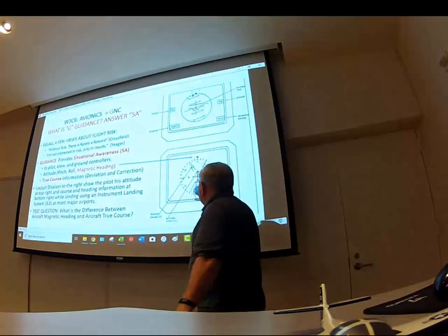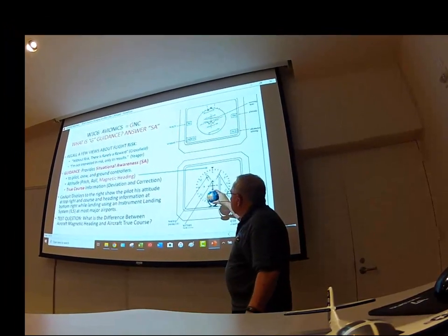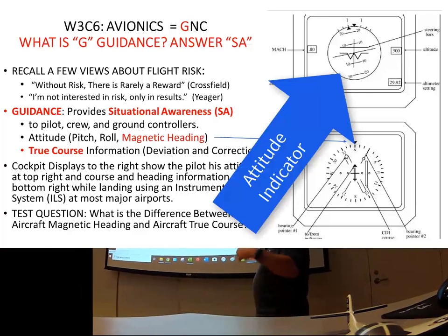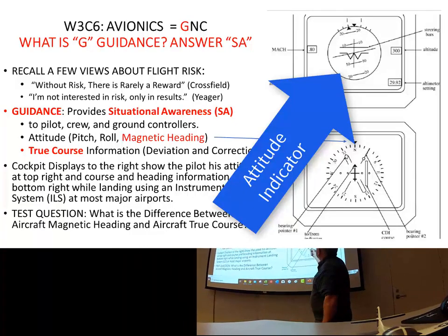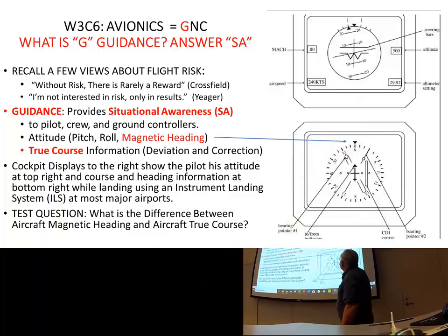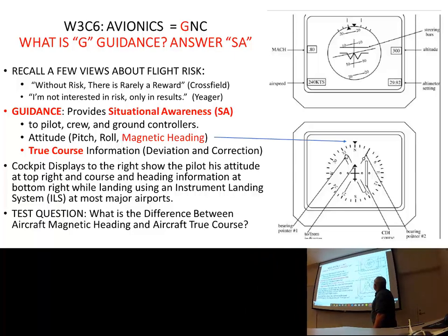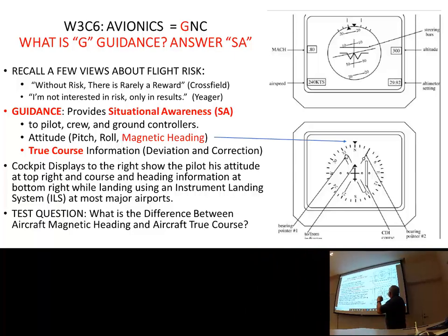It's in the cockpit like this, and if I pitch up, then the ball goes like this. It just shows me a pitch up. If I roll, the ball goes like this. It shows me I'm rolling, right? So that little ball moves around in the cockpit, and you can see the numbers 10, 20, there's 10, 20 degrees for roll. So here's the roll axis. Here it shows the pilot what his bank angle is, and there's the pitch axis, which shows how high up he's moving. The little W means landing gear.